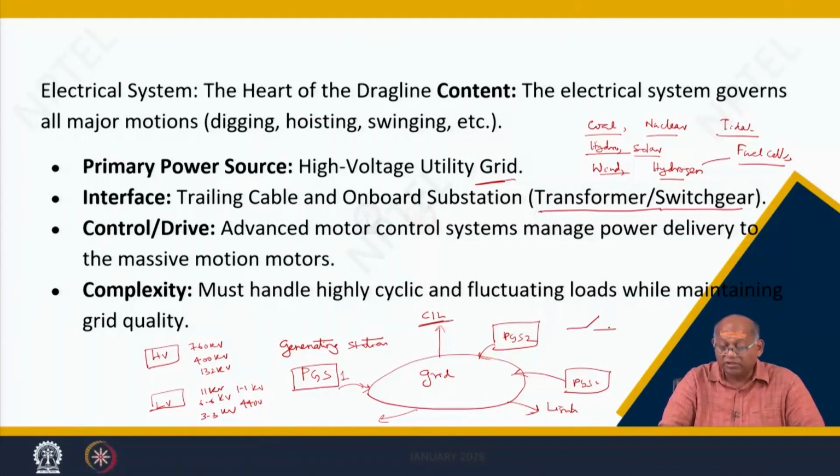It is a switch which will close and open, but it is not an ordinary switch, because the ordinary switch you see in your home is a very low voltage switch which can be operated by hand, but these are very high voltage, also high current. When you switch off a high current, there will be flashover. Therefore, that flashover has to be protected. Therefore, these are called switch gears, and they cannot be operated by hand. They have to be remotely operated by motor mechanism, so by some kind of automated relays.